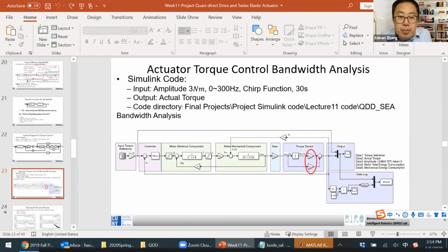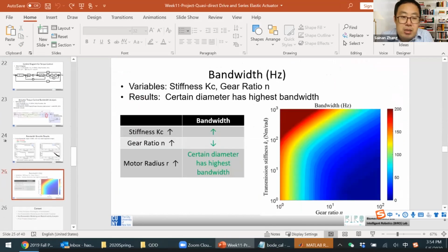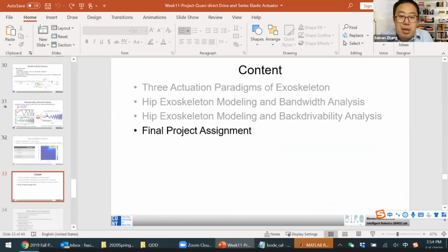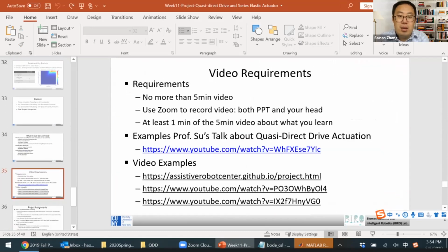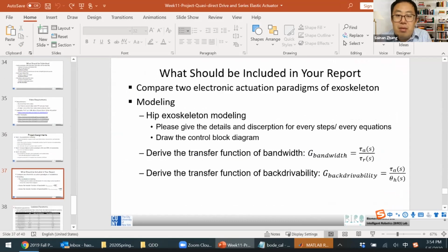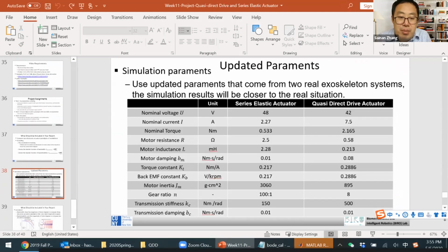You see, series elastic actuators typically are kind of like a pancake, and a conventional actuator is typically like a sausage. That's why they have different diameters. But I think we already fixed this diameter, so I don't think you need to tune that. Just keep it as it is, because this is related to the manufacturing of the motor. You don't need to tweak this parameter.